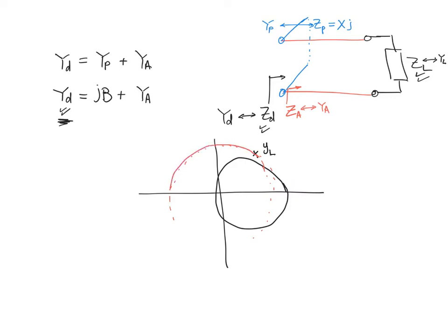So simply I can plot this other circle coming from the movement over the transmission line, which will have YA somewhere, but for sure it has YL, right? So this YL allows me to know how to draw the circle, while knowing the desired impedance gave me the real part that allowed me to plot this other circle.